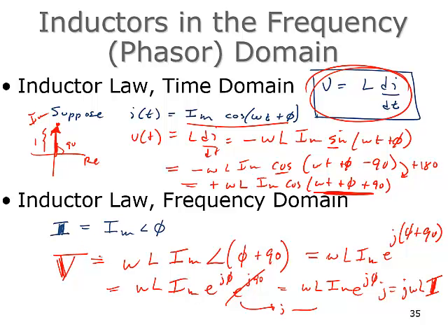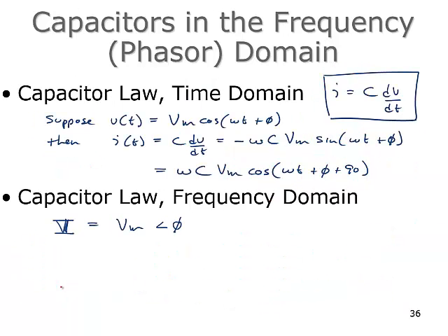And here's where Brock's acronym comes in, right? The voltage is going to be 90 degrees ahead of the current, right, because we're doing phi plus 90. So we could say VLI, or in physics, ELI. You have the voltage, and then you have, of course, an inductor, and the voltage is ahead of the current, right? Well brought up there, Brock. Okay, so yes, and the capacitor works the same way, just kind of speeding up a little bit.